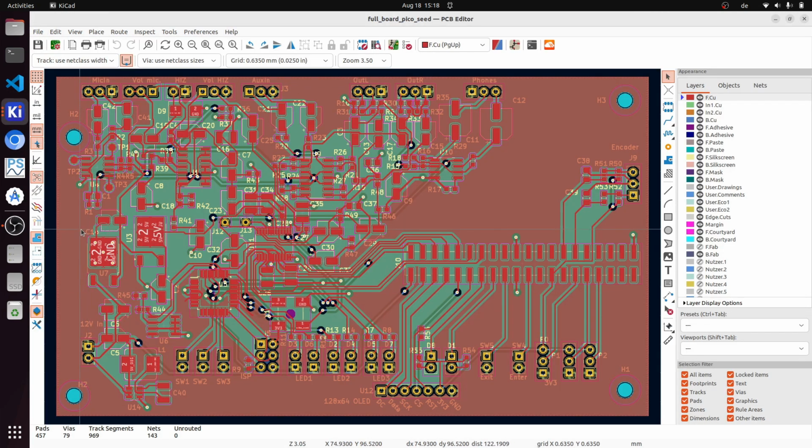One basic principle I applied is that I tried to physically split the analog and digital parts. So analog is everything on the top part. Here you see the microphone input with one of the op-amps, the NE5534, and the other op-amps built around the analog part. It's all on top, meaning above this virtual line we have here.